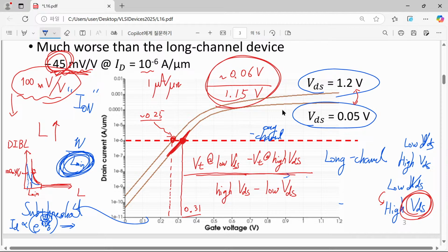Dibble, according to DIBL, we will have a reduced threshold voltage. Well, now we understand that, compared with its long channel variant, we have a relatively lowered threshold voltage. As much as we understand this phenomenon, can we use it for our circuit?